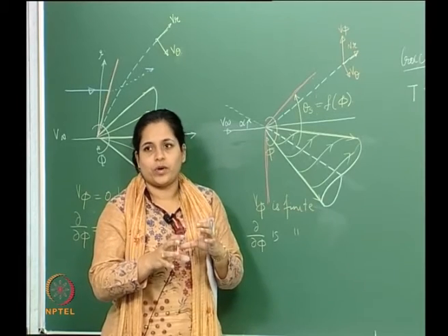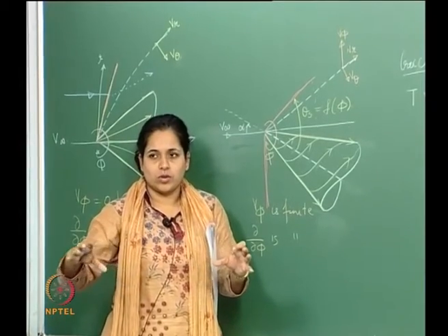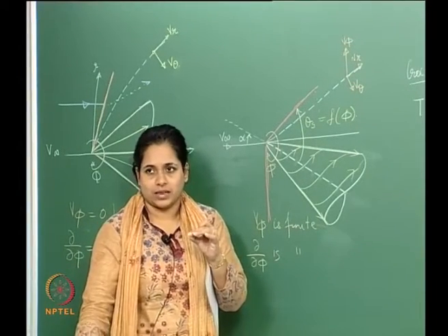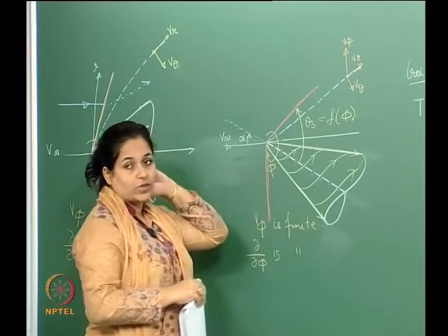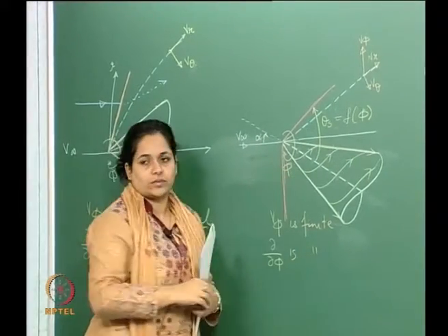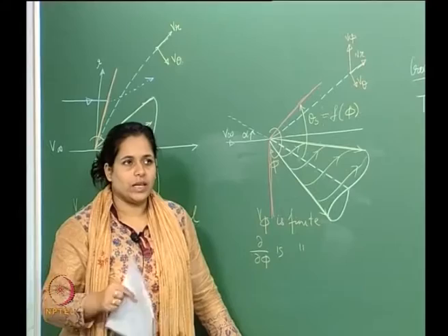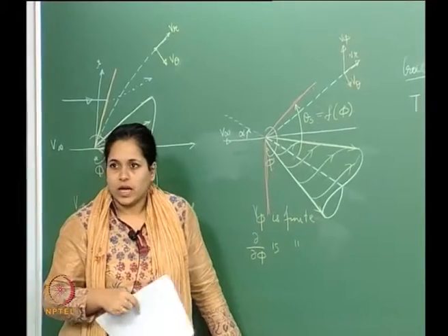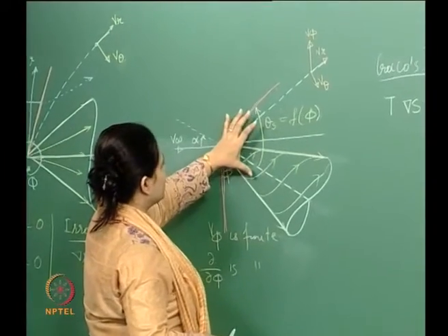Now, when I move from one point to the other, since this cone and the shock are not symmetric about the z axis, the angle of the shock in the phi direction changes, which means the shock changes, which is almost equal to saying that we encounter a different intensity of the shock. I think that would be fair to say. So, I encounter a different shock.